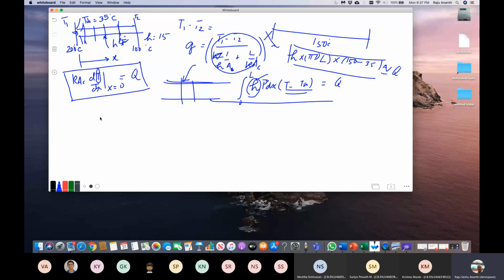So we know the temperature distribution, T minus T infinity, which is theta. We defined it. It's going to be A e to the power of mx plus B e to the power of minus mx, which we know because the calculation was K, the cross-sectional area, d squared T over dx squared, minus H P (T minus T infinity), plus 0.